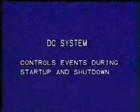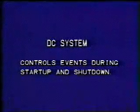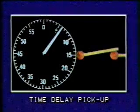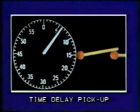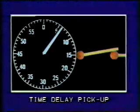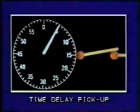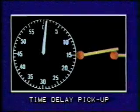You have just viewed the lesson on the electrical system. Let's review the important points. The DC system controls the sequence of events that occur during the startup and shutdown cycle. Two types of relays are used in the system to time the sequence of events. When the time delay pickup relay is energized, a timer begins a preset time period. After the time period is over, the contacts transfer.